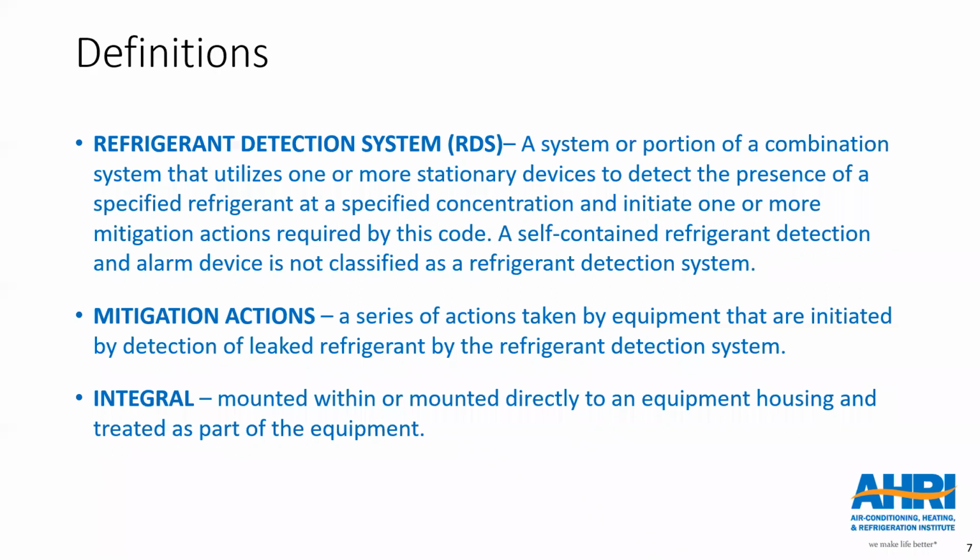Okay. So I've been using some of these terms already, and they show up in standards, so I want to go over these definitions before we get into the details of the standards. So a refrigerant detection system, which I'm going to call RDS later on, is a system or a portion of a combination system that utilizes one or more stationary devices to detect the presence of a specified refrigerant at a specified concentration and initiate one or more mitigation actions.